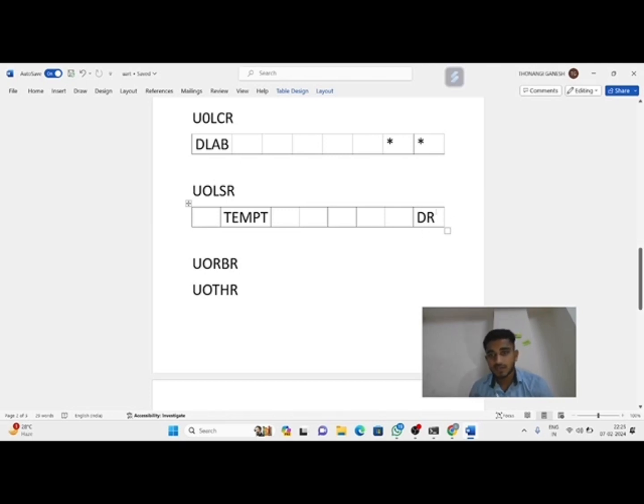Then the data ready bit is for checking whether my data was successfully received or not. Like the temporary buffer of the transmit hold register, there is also a receiver buffer, which is our U0 RBR. While receiving, reception starts with an initial bit of 0. Whenever 0 occurs on my receiver pin, receiving starts.